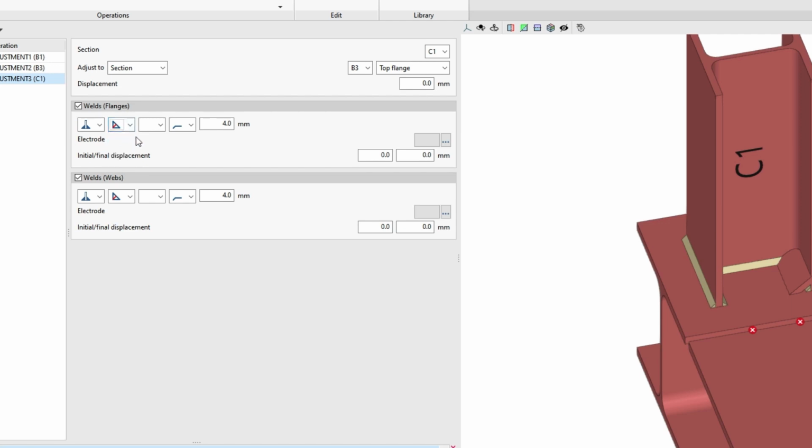In the third drop-down menu, we set the shape of the weld surface, whether it is not defined, flat, concave, convex, or with toes blended smoothly. In the fourth drop-down menu, we indicate the place of execution, either on-site or at a workshop. Here, we define fillet welds by means of the throat thickness at 3.5 mm.